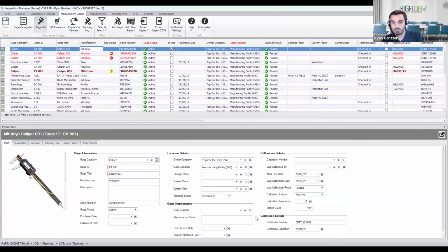Additionally, you can set up your calibration interval based on that usage history. You know, if you got a gauge you're using every, for example, say 6 months, doesn't necessarily make sense to be calibrating it quarterly, right? Things like that. So from an efficiency standpoint, there's benefits as well.